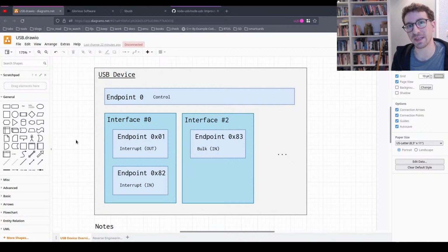But we don't have to implement the HID, which stands for Human Interface Device. We actually only need to implement the control endpoint. Although it's not the control 0 endpoint in this case, because they've decided to do something non-standard, of course. We're going to implement a higher level control thing. So we're just going to be sending control commands to this, which allow us to configure the LEDs and the macros and switching profiles and that kind of stuff.